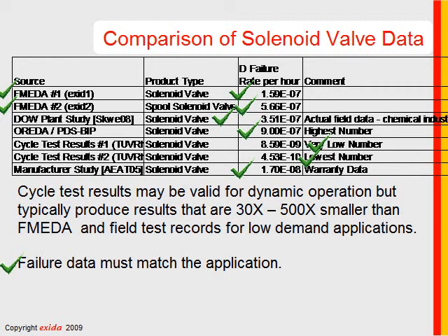There's something. Oh, that's good. Thanks. Hold on. Let me read this out loud. I work in operations, and I'm more interested in field failure rate measurement. The problem that I have is over a few years of the life of equipment, the dangerous undetected failure rate is very difficult to obtain. Yeah, I agree. On the other hand, safe and detected are much higher, yes, and we get some numbers. I use the safe failure fraction to get a calculated dangerous undetected failure rate to validate the PFD calculation. Is this the right way of doing that?